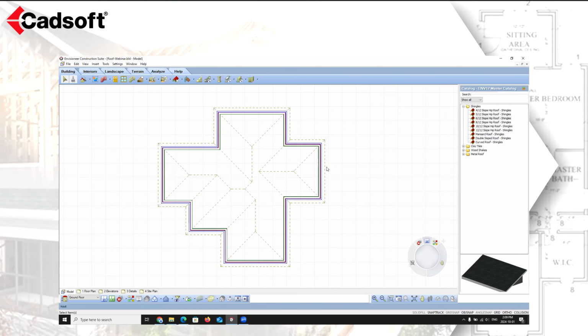So if I select an edge of the roof, you're going to see that the arrow turns green. So let's change multiple surfaces simultaneously here. We're going to select this edge to be green, and let's change a couple of our different roof edges to be green as well. So let's place a marker here, here, and here. So let's say we want gable ends on these four edges of our roof. So by just simply selecting each of those arrows, we've now made those the currently selected roof edges, and they are now highlighted in green.